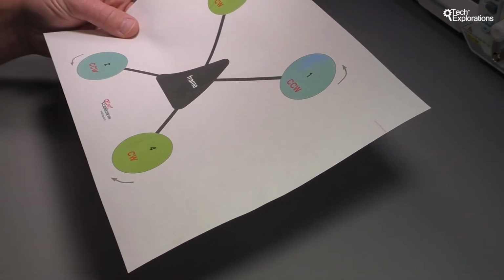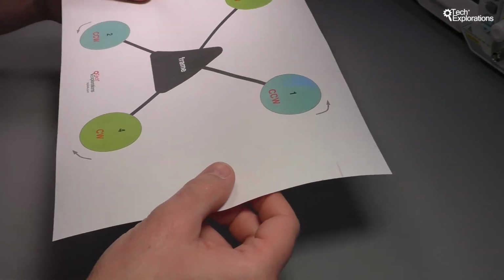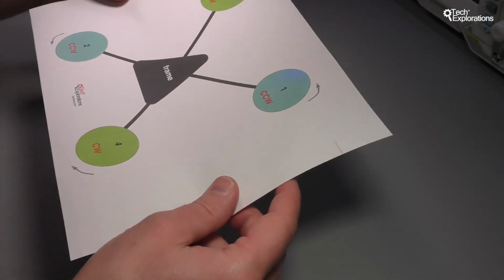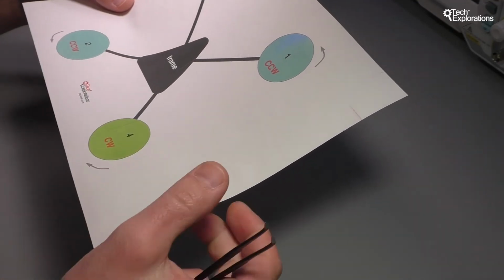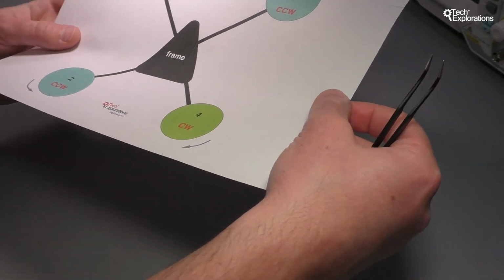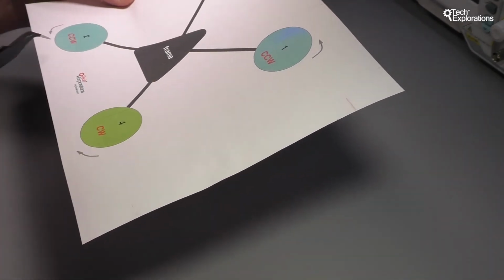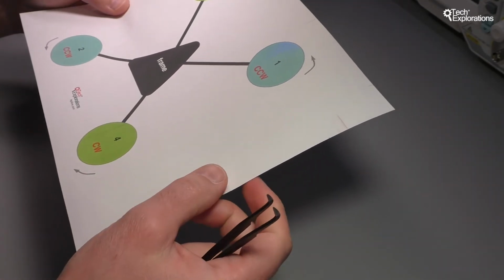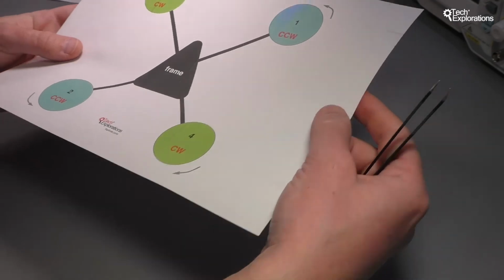And because these two motors are rotating faster than the other two motors, the whole frame, the whole drone, will move clockwise. And I guess you can guess, if you want to get your quadcopter to rotate counterclockwise, all you've got to do is get your flight controller to increase the speed on motors 2 and 1, which are the ones that are rotating counterclockwise. So you get that motion.